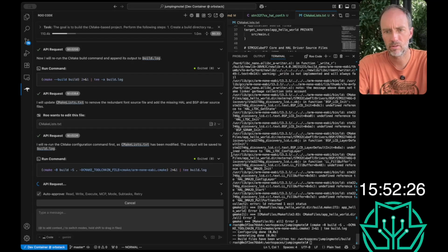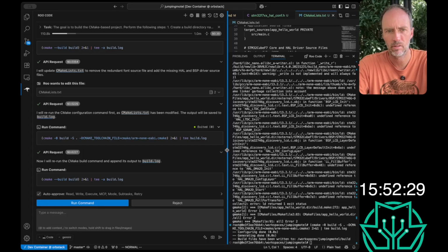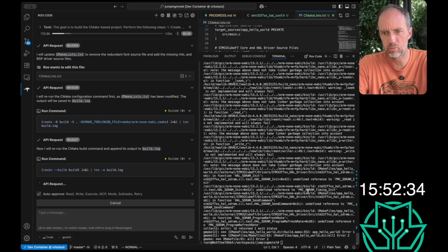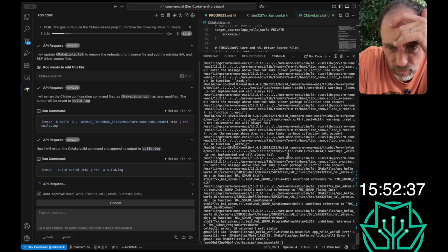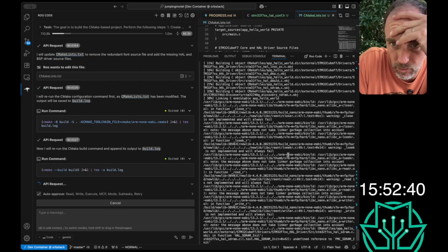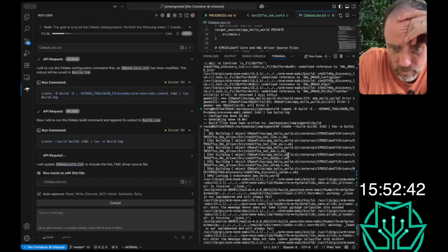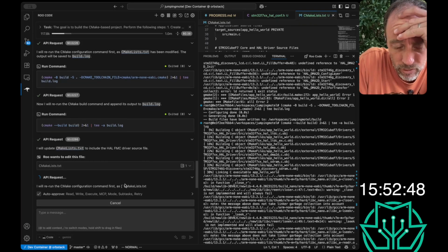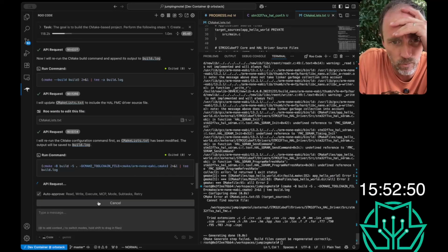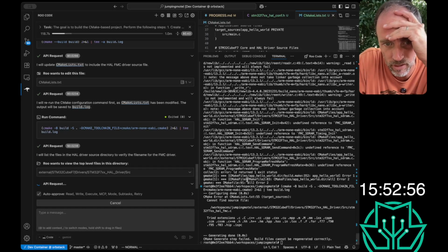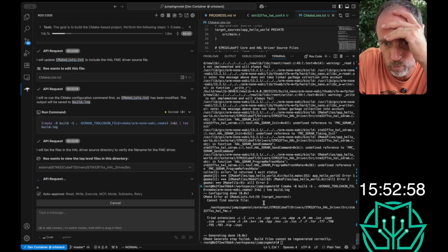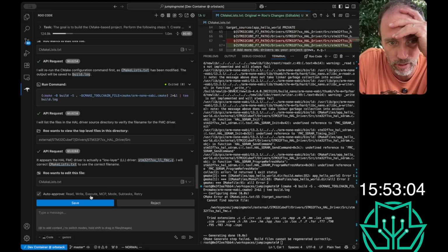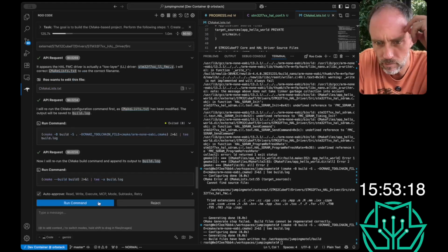Run command. Okay. Build files have been done. And run command. Poof. Undefined reference. FMC SRAM. Maybe you should include the SRAM stuff too. 38%. HAL FMC driver source file. Okay, run. Cannot find source file. It's actually a lower layer driver. Okay, there you go. Fixing the CMake file. Thank you. That was successful.